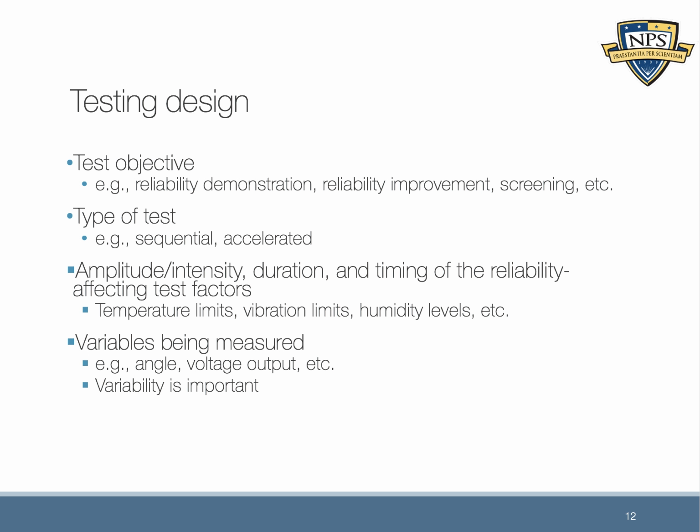It's very common during burn-in style testing where there's temperature cycling and random vibration to cycle the units and power them up just during certain times. And so you may, during cold soak, power the units up, test them, make sure that all the variables are correct, and then turn them off again.